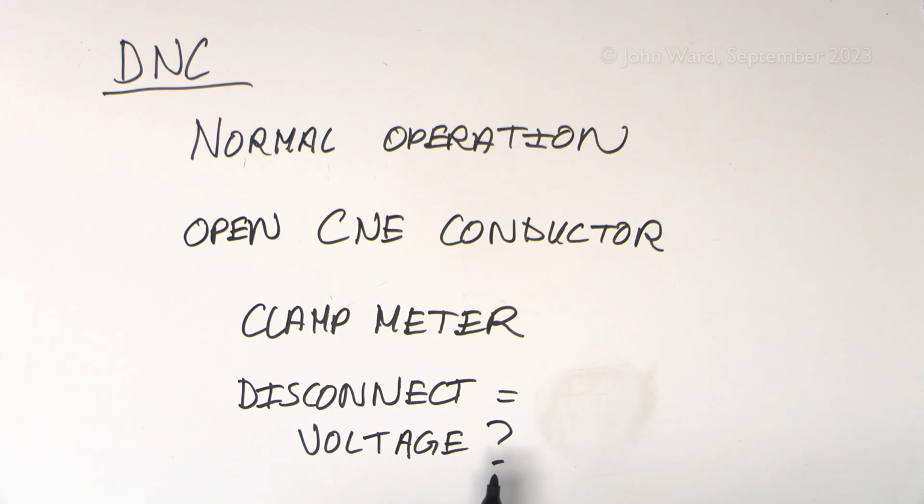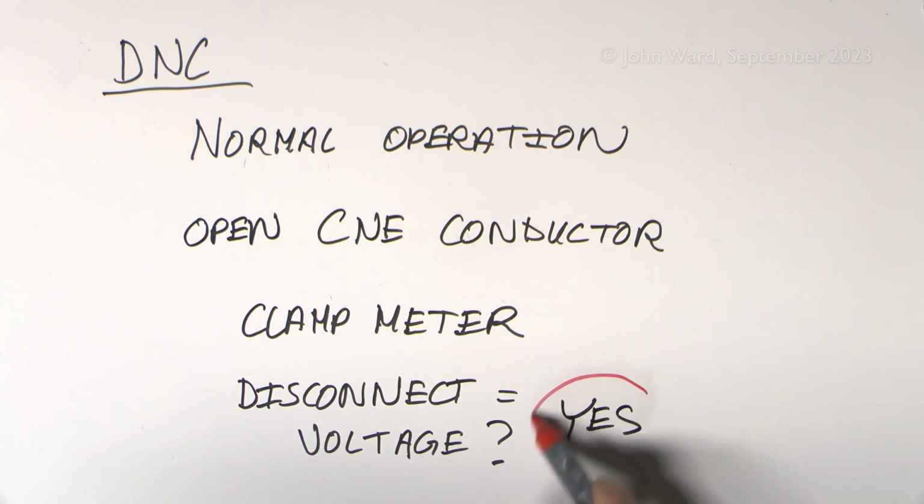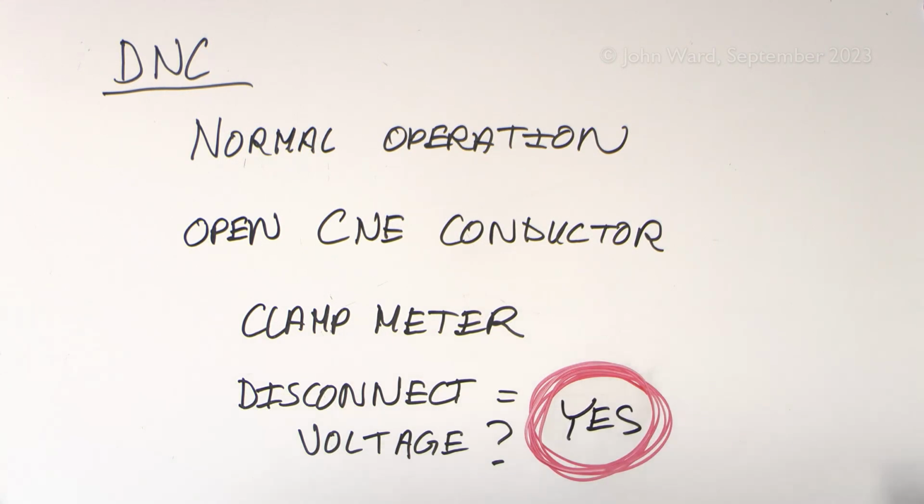And you need to check this with a voltage indicator, preferably a single pole device with a contacted metal end, because bearing in mind using a 2-pole thing here, what's the other pole going to go on to? You can't really just stick it on the main earthing terminal in the installation, because that could actually be where the problem is. So, single pole voltage indicator, is there any voltage there? If there is, then this of course is a huge problem. Dangerous situation has been revealed.